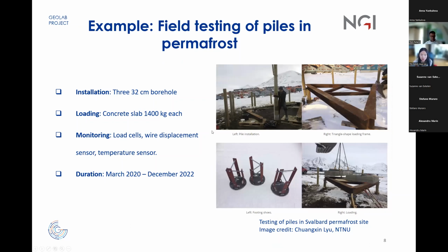These pictures basically summarize the test. First, 3 piles of 33 centimeters each were installed in pre-drilled boreholes, as the pictures on the left show. Then we set up a triangular-shaped steel load frame. The load is induced by concrete slabs, each of 1.4 tons.